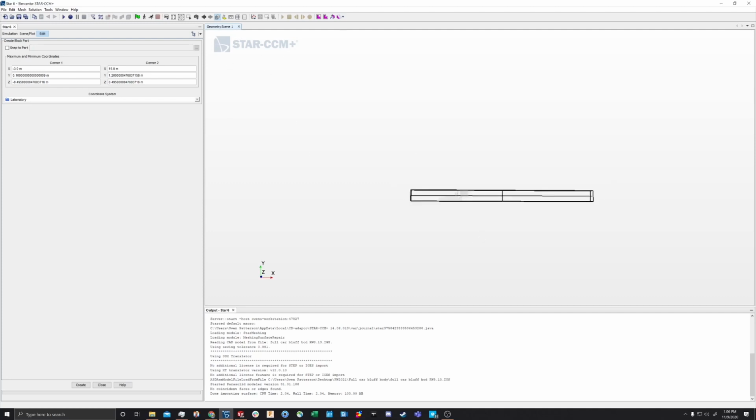Obviously this whole box creation isn't supremely precise. There are some bits that do need to be precise. You want your ground to be in the right place, but it tends to relate to how much computational intensity you're willing to handle and how much accuracy you want in the sim. If you make your box bigger, you're going to get more accuracy, but it's going to take longer to run. So that's a trade-off there.